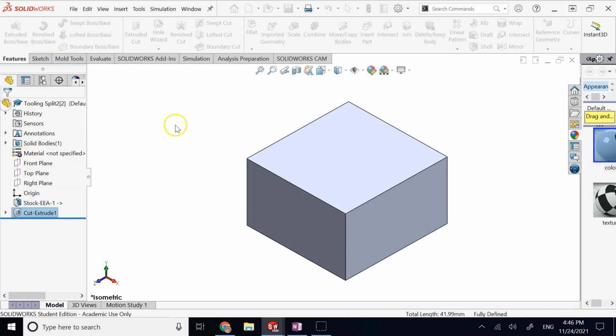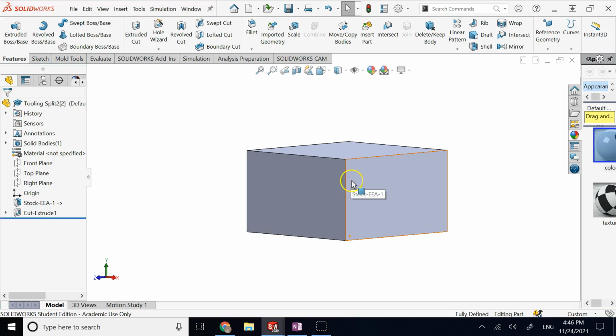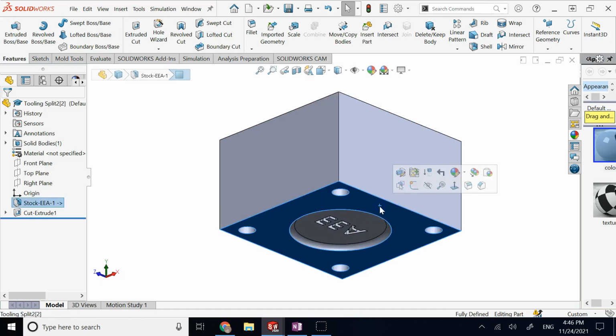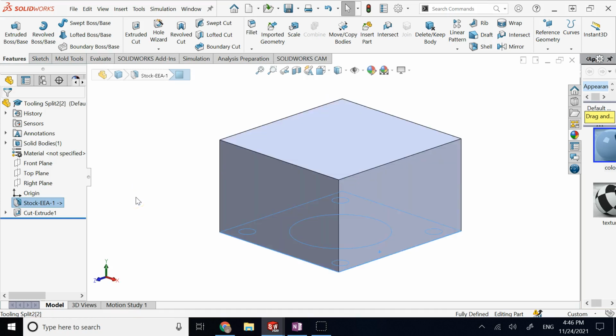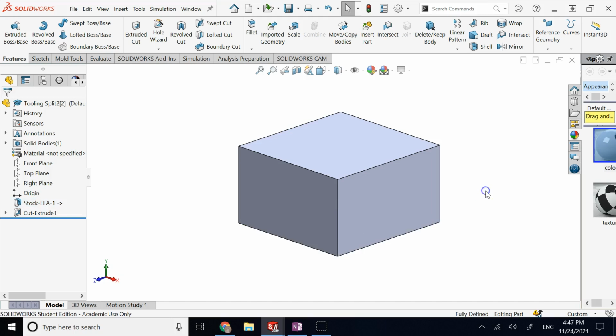So the shafts are completely inside the holes and there is no room for them to have any gap between these. So this one can perfectly sit on the bottom one without any chance of, again, the shaft is longer than the hole, and a little bit just because of manufacturing errors, there will be some gap. So I make the holes a little bit longer than the shafts.